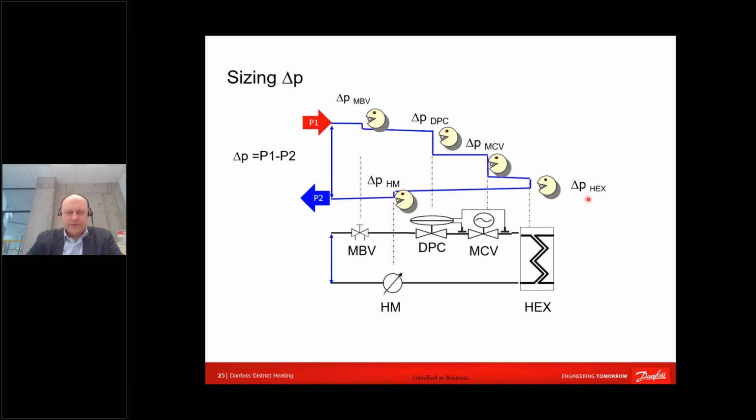When we are sizing things, we have to know that we will have to dedicate pressure to each and every component. Here probably I have to address one question to the sizing of a flow if we are sizing differential pressure controllers to several components. Our practice from international and national projects is that if a differential pressure controller will be selected for a single or several circuits, there are two scenarios we were using often.